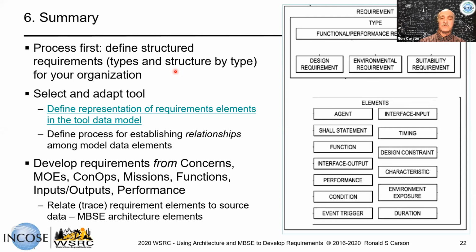So you can represent those elements, and whether it's 3 parts or 4 parts or 2 parts or whatever the elements are, like CORE and other tools have the ability to select what the verification method is. So that becomes part of it. You select that, that's built into the tool. So I just click the method I want. You need to define the conditions under which the verification is going to happen. It's going to be some subset of throughout the flight envelope, for example. So you have to define that, and that can be captured in the tool.